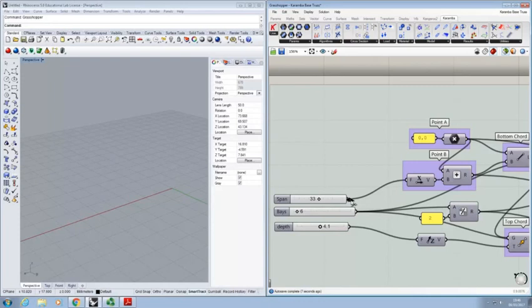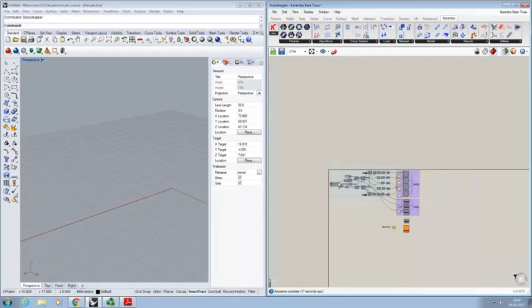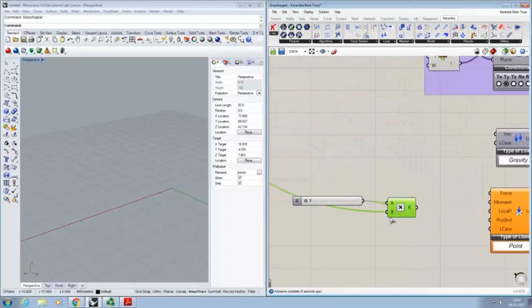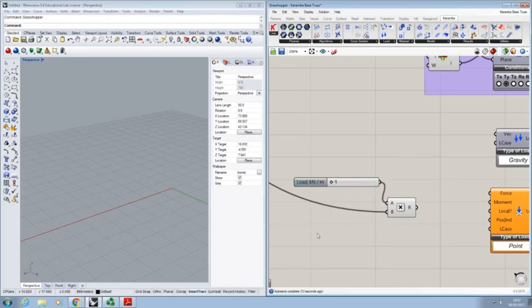So one of the other sliders right at the beginning of the definition. And what that means is that now this slider has turned into load in kilonewtons per meter. And by changing this and multiplying it by the span, we have the total load applied to the truss.